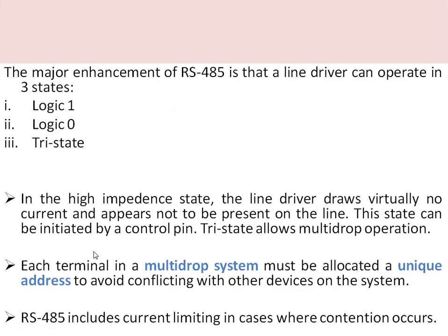So the major enhancement of RS485 is that it can support three states: logic 1, logic 0, and another state, the tri-state. The tri-state is the high impedance state that allows RS485 to be operated in multi-drop operation. In multi-drop operation, whenever the driver is put in high impedance state, it will not draw any current, and it is not present on that line.